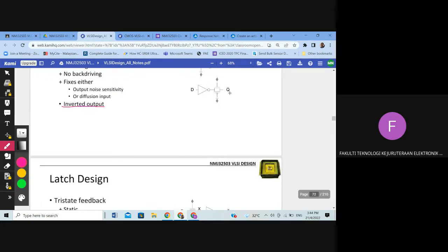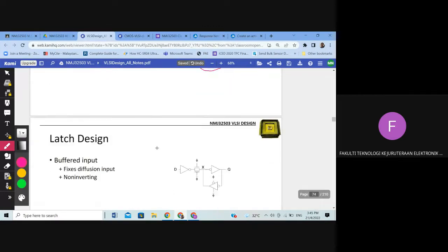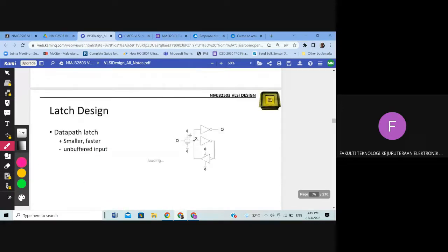Then designers improved it. Now it has another feedback loop, which is this one, that makes the latch have a memory, with an inverter feedback. And as we go down, we have the final design of the latch, with the transmission gate and also the buffered, inverted output here.